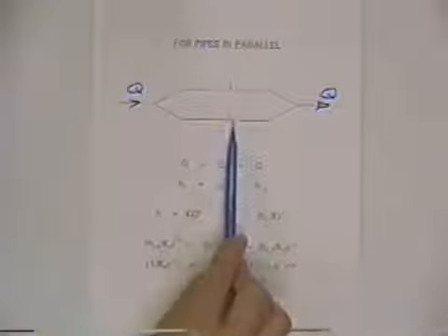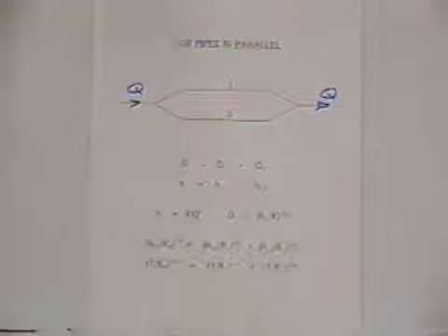And likewise, there are comparable relationships between pipes in parallel. If you've got a couple of pipes in parallel, it reverses. Remember, when they're in series, the flow rates are the same. But when they're in parallel, the total Q, the Q right here, which by continuity has to equal the Q right there, is just going to split. The Q in this pipe plus the Q in this pipe is going to equal the total Q.